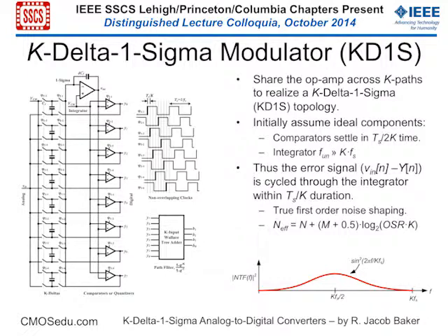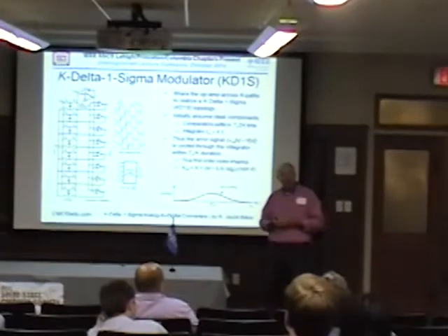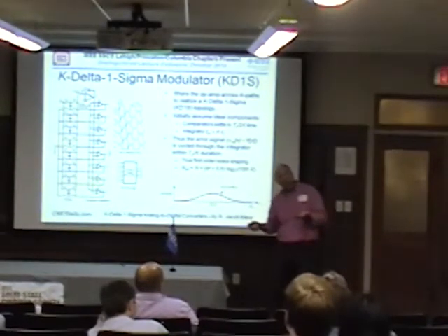So one problem with this technique is you need to have a delay lock loop or something to generate the phases of the clock. There's applications where you're trying to digitize something over a finite reference and you can simply use 2 logic gates.